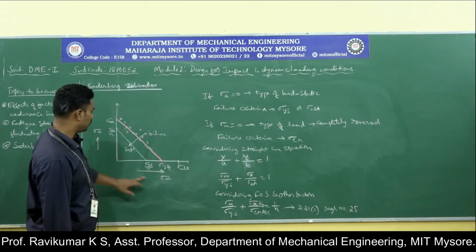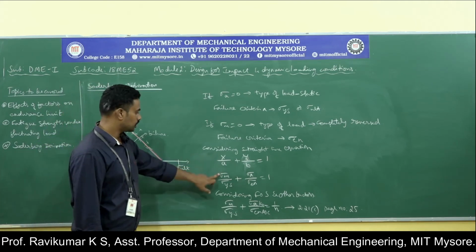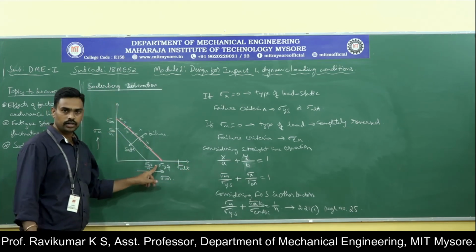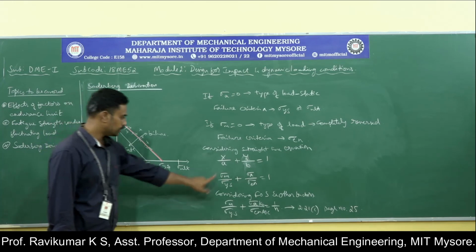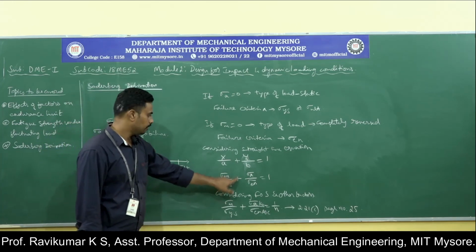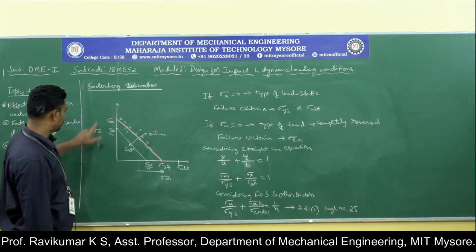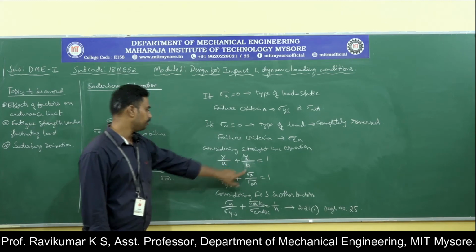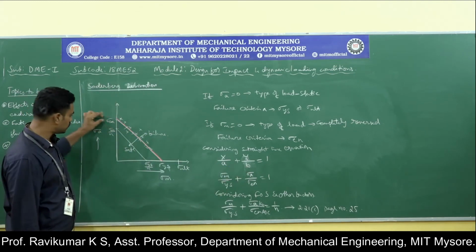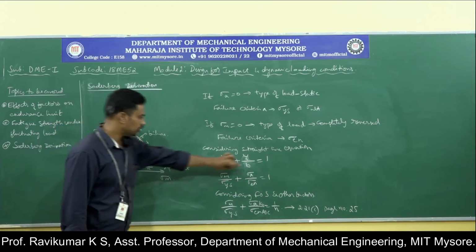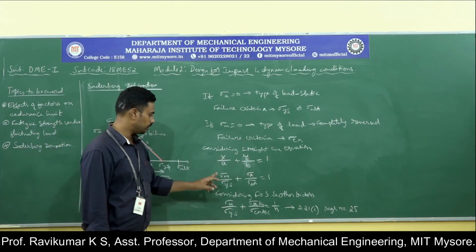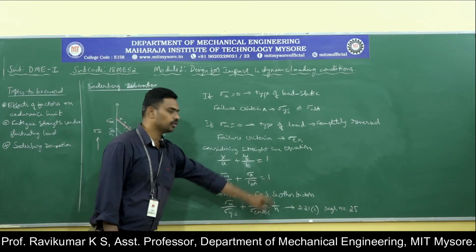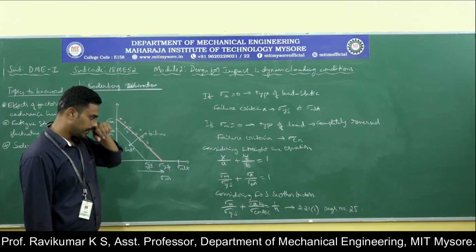So, in x, we are going to consider mean stress. So, substitute in the place of x mean stress. A, the intercept on the x-axis, is yield stress, sigma ys, substitute at the place of a, sigma ys, plus y-axis. In the y-axis, we have considered amplitude stress. So, y replaced with sigma a. Then b, on the y-axis, we mark endurance limit here. So, b is endurance limit. Therefore, mean stress by yield stress plus amplitude stress by endurance limit is equal to 1 is the Soderberg equation.